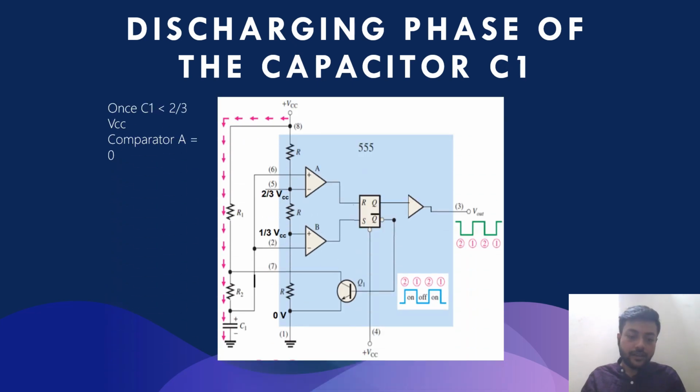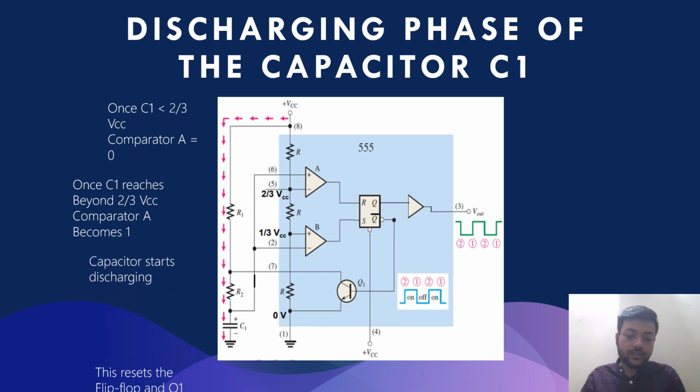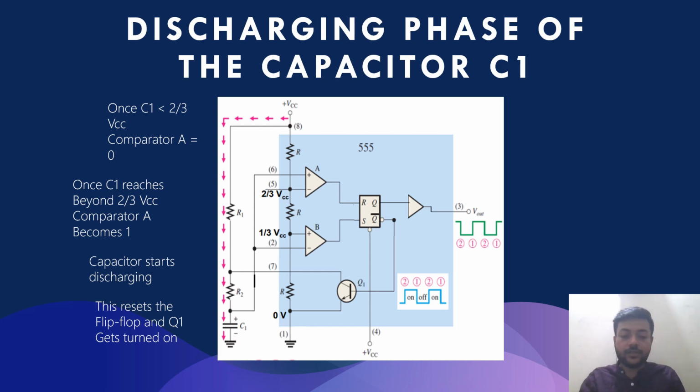In this diagram, power up and initial charging. When we turn on the circuit, the capacitor C1 is uncharged. This triggers the 555 timer to output a high voltage VCC at pin 3. Capacitor charges. While the output is high, current flows through resistor R1, charging capacitor C1. The voltage at pin 2 connected to C1 gradually increases.